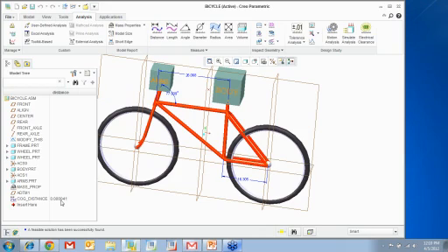All right, so this is behavioral modeling. You want to design your model such that it behaves in a certain way. Now, another use case for this is, say for example, we are designing a crankshaft, and we want the center of gravity of the crankshaft to be right on the rotation axis.